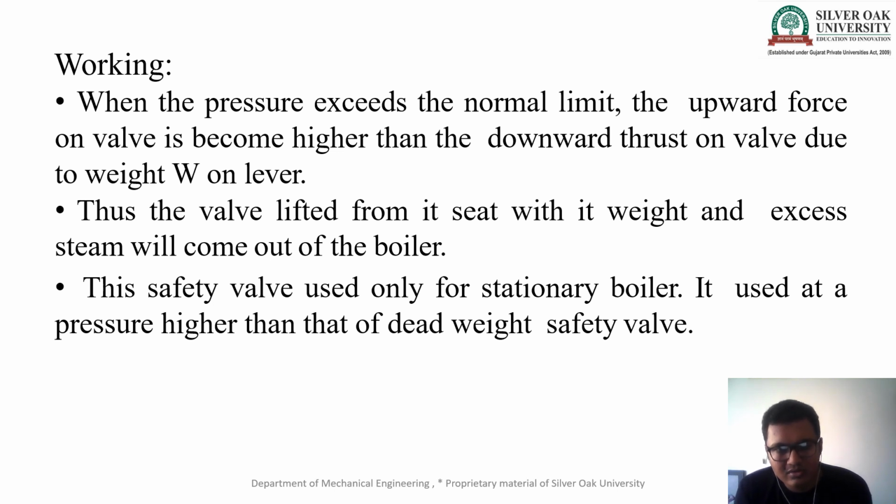Here also, we are not using this valve in a movable boiler. If we use it in a movable boiler, what happens? The movement of the weight is slightly more, and due to the movement of the weight, the downward pressure set by the safe limit gets disturbed, and if it gets disturbed, the valve is lifted even within the working pressure.